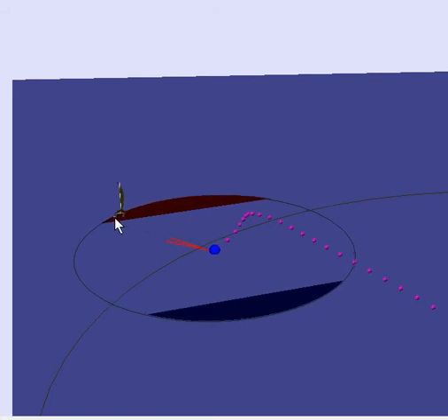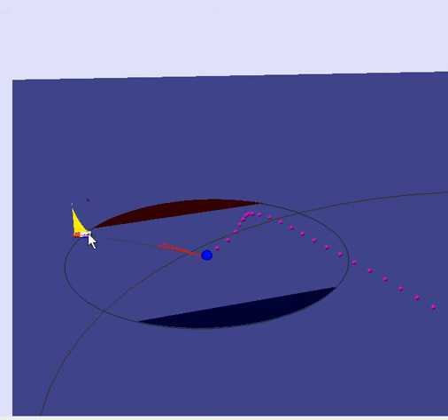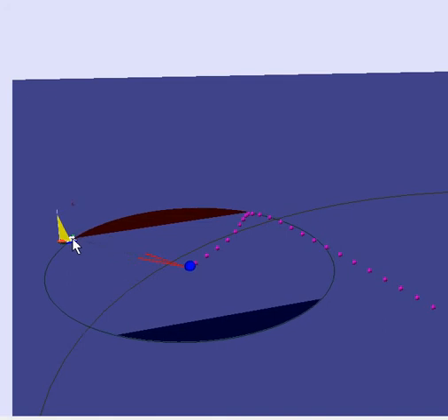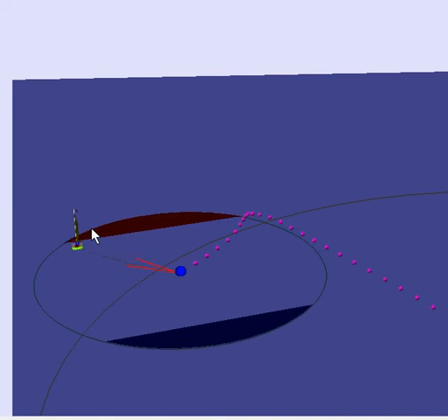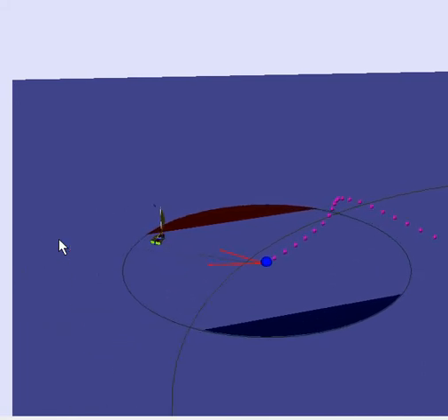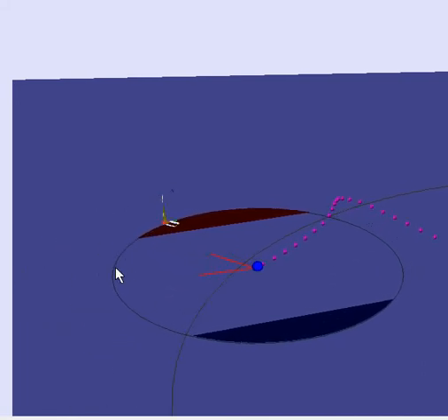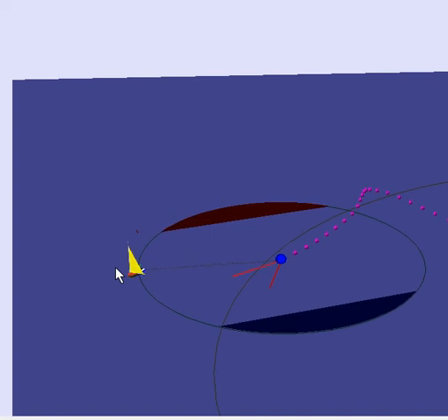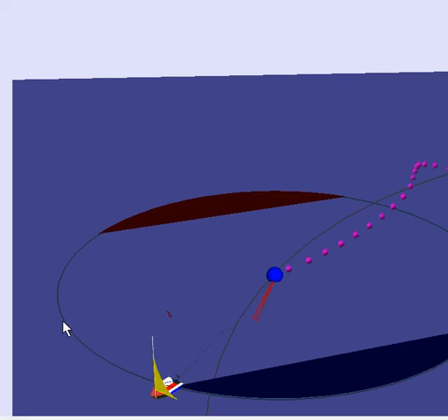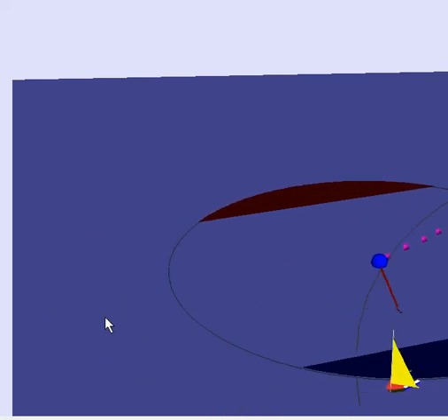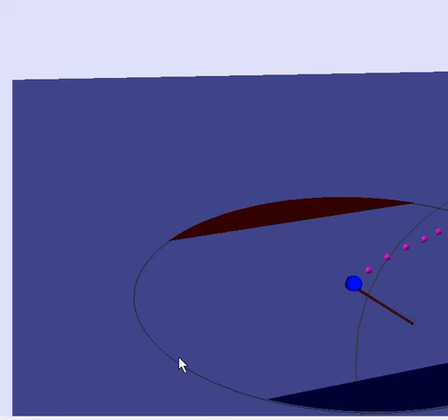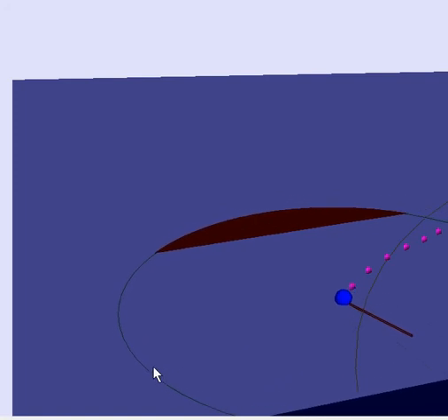So at this moment, what is a segment? A segment is an arc where the robot goes in a direct and an indirect sense. Some arcs are unfeasible. For instance, this one I show with the mouse does not correspond to a feasible segment. Why? Because the robot is able to follow this segment downwind, but not upwind. It will have to maneuver.